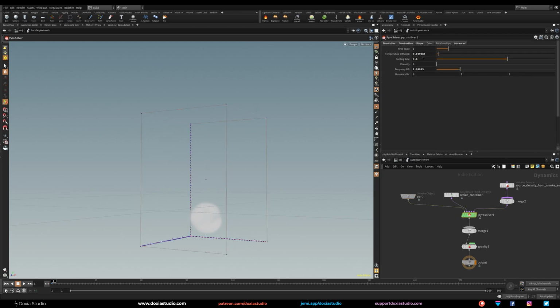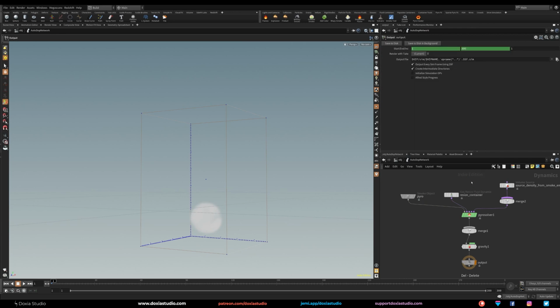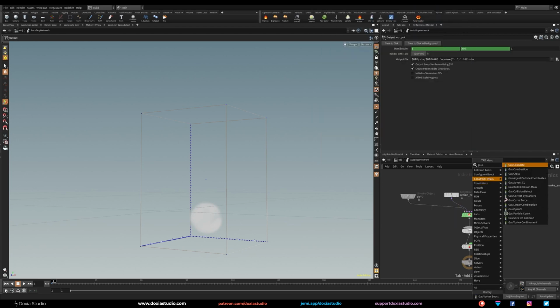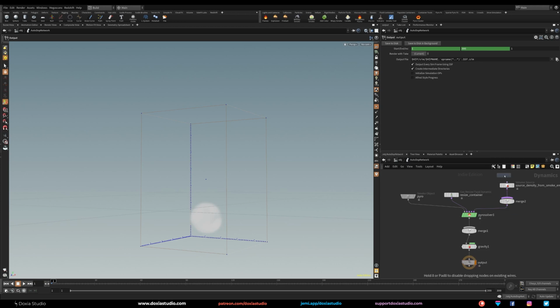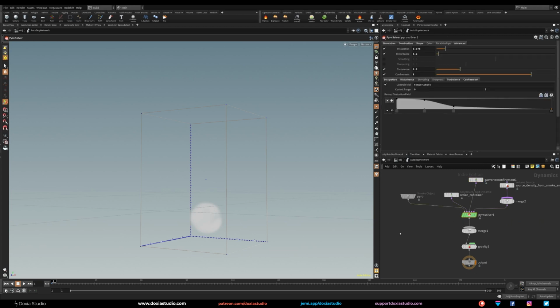And let's change a little bit in the pyro solver. Okay, we want this to go up. And our shape dissipation is all right. We want to lower down the disturbance, lower down a little bit the turbulence, and we want a lot of confinement because we want that vortex, right? You can even put here a vortex boost. Oops, not this one, sorry. Gas, how is it called? Confinement. Gas, let me try to look for it. Gas vortex confinement, it's not boost, okay? And link this to the velocity update. It will add more of those vortex, okay? That puffy trick.